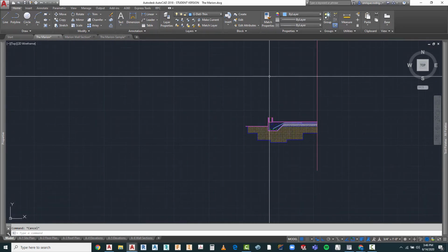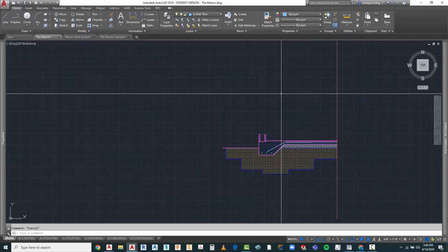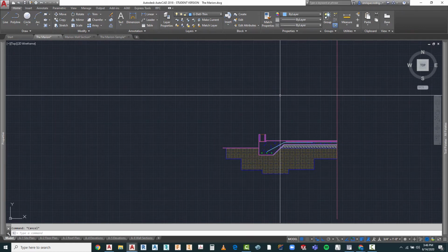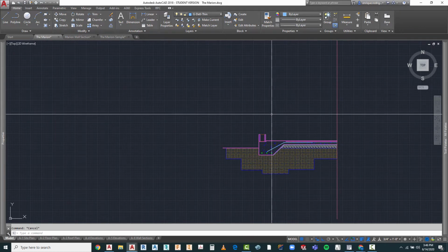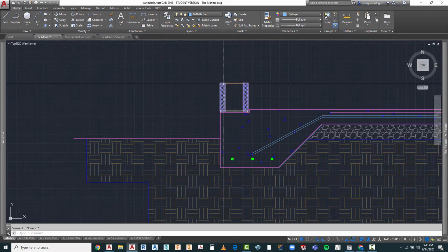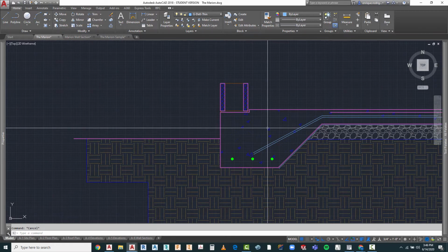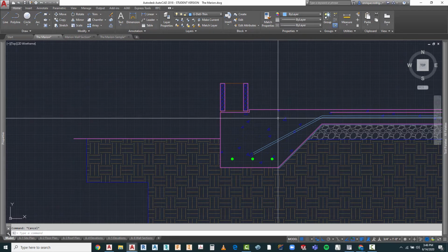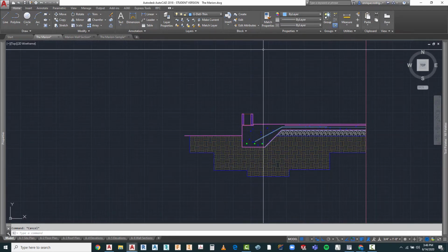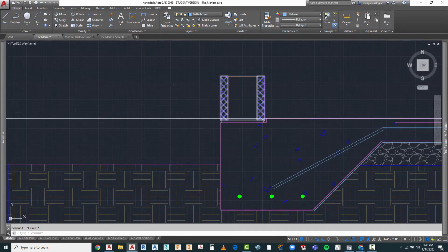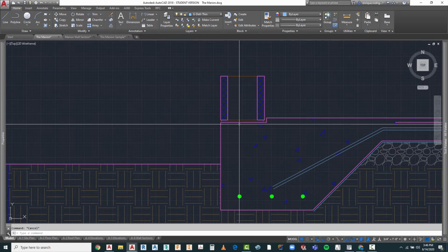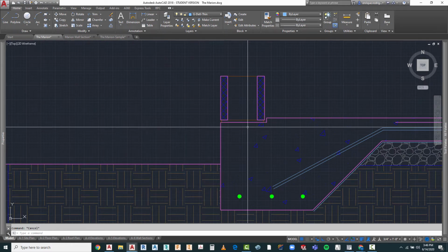Now the height of this is going to be determined by a couple of things. We wanted our ceilings roughly to be about 9 feet, but because construction is a modular type of construction, especially with block, we're going to be a little plus or minus on each one. We're also going to have this recessed 3/4, so we're going to modify it slightly.